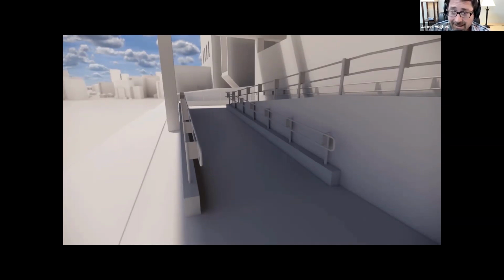If you create model in place elements inside of laser scanning, that is best practice. However, you don't want to have a library of model in place elements that can accidentally be grabbed. Model in place elements can have wonky things happen where elements inside of it can shift around or disappear. So basically these were modeled in place first. And then after that was done, we did, and you guys need to Google this if we don't have time to show it, you can actually grab the model in place element. In this case it's made up of, I don't know, 60 extrusions and some sweeps and such.